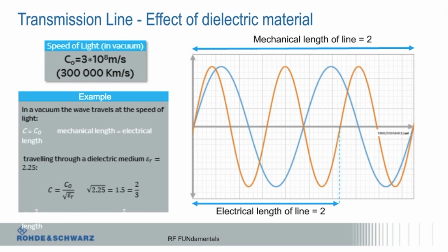If you get a bad cable and you say, okay, I want to measure all my S parameters of my device with a bad cable, and then I look at a good cable, after you've done the calibration and you look at where is my residual S11 of my cable at the calibration point, you might find with a bad cable, and I've seen this, it might be 20 dB, right? That's as good as it's ever going to get.